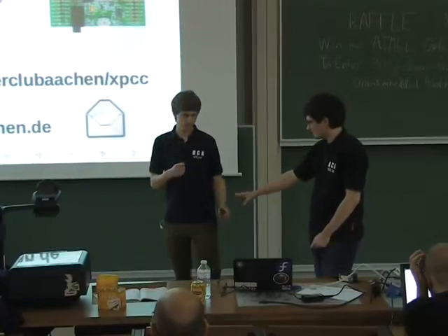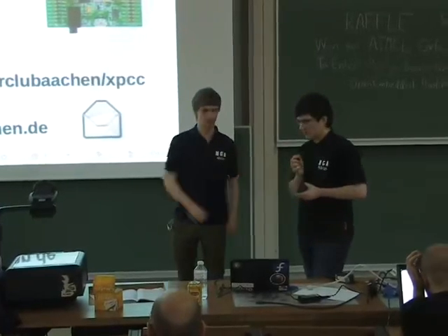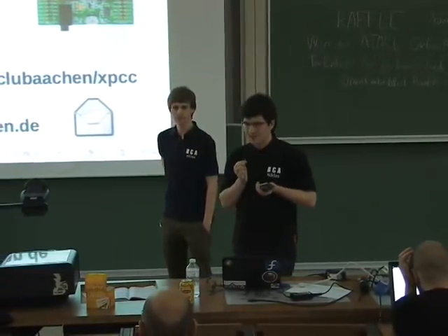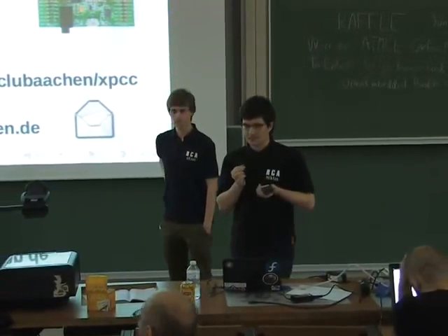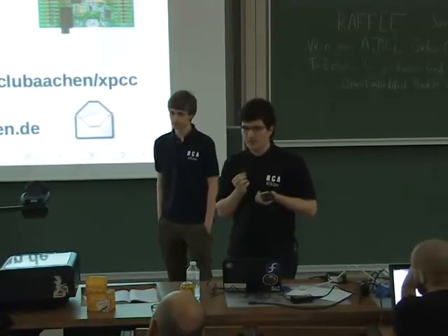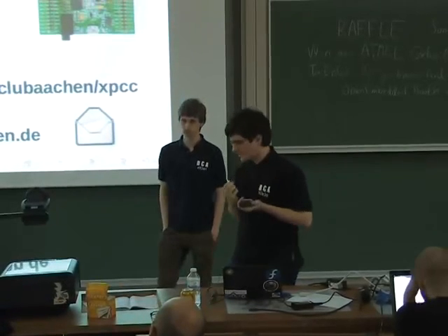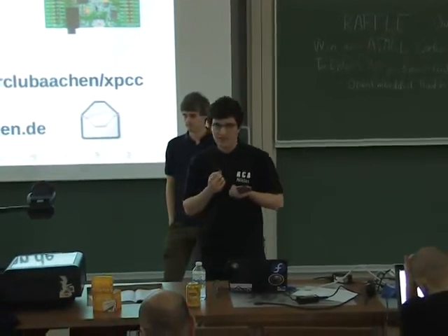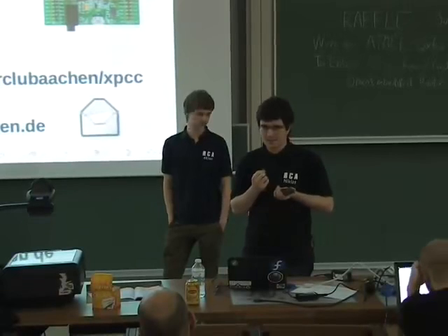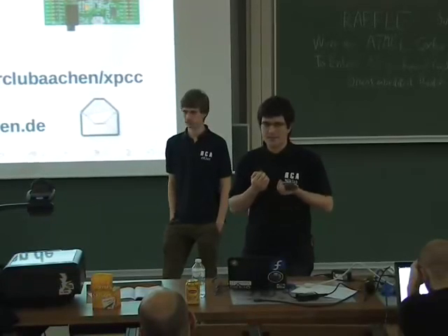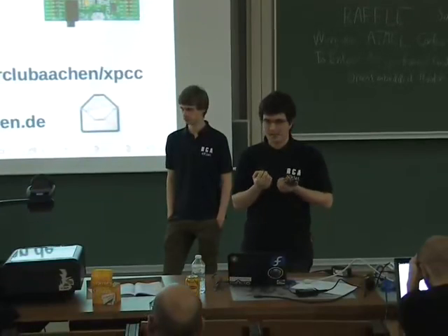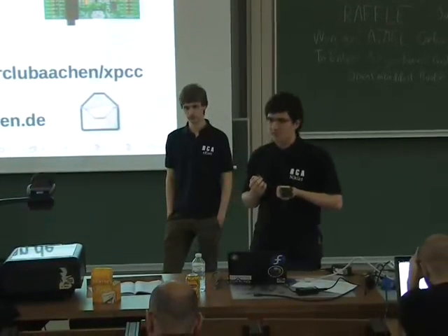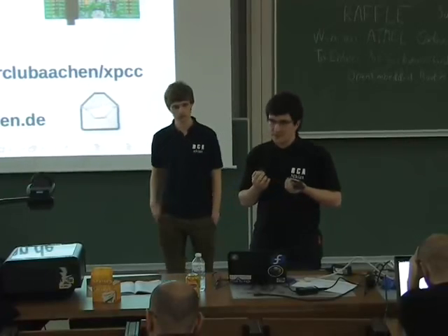For normal people, to translate that, essentially we use static stuff, and we try to avoid function calls. As he said, most of the code is in header files, and we aggressively inline manually. For example, if you only set a bit on a register, the entire function is inline, because you can't do a function call in less. So we have to manually optimize this sufficiently.